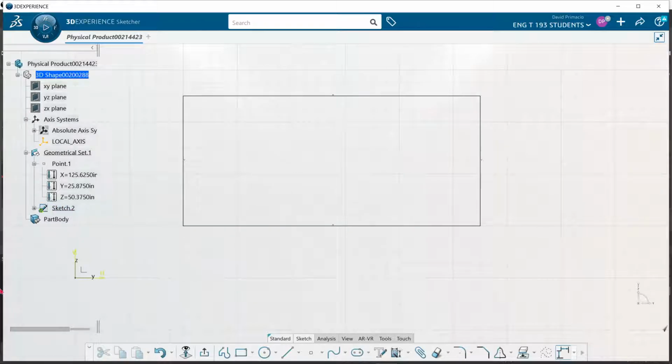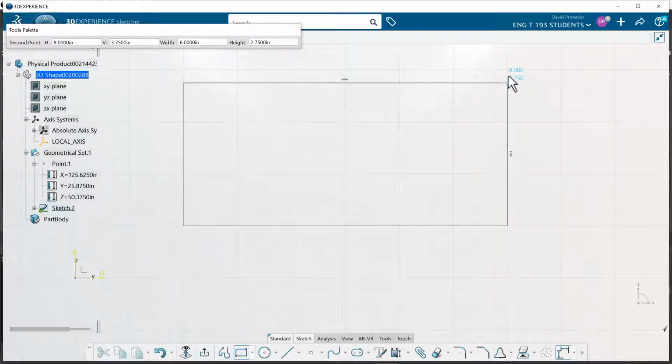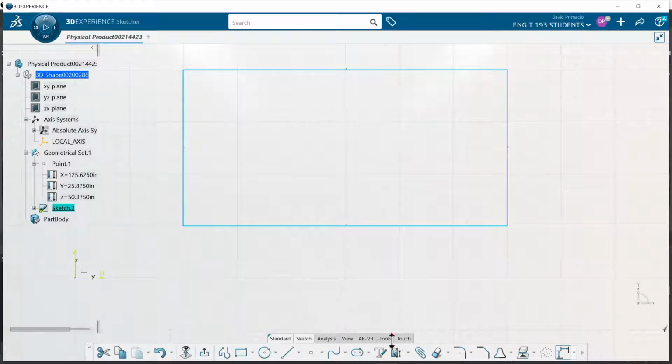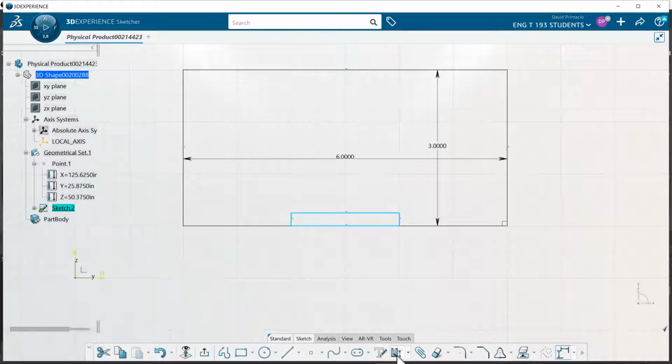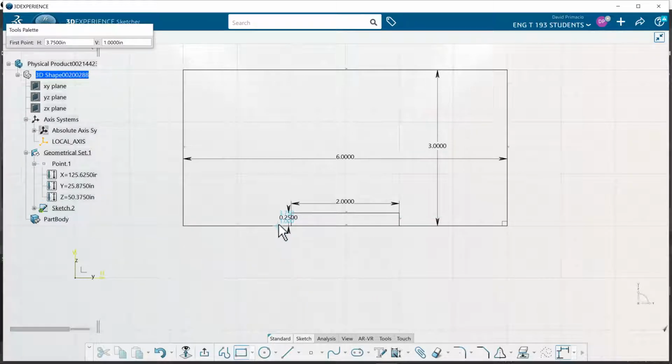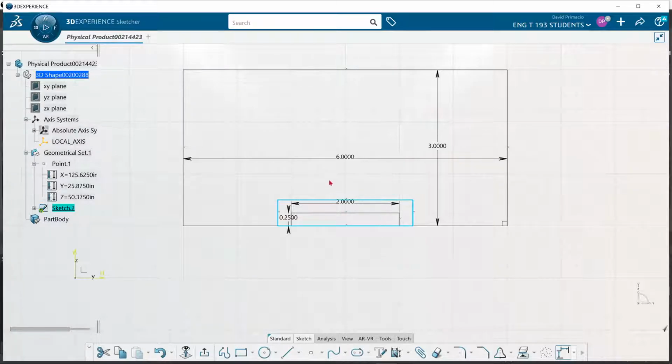So if I were going to do this, what I would do is when I create this first rectangle, CATIA does auto constraints really well on boxes. I just hit that and hit OK and just let it do its thing. I'll create another rectangle, and with it highlighted, hit auto constraints and just say OK. What I'm doing is I'm just controlling the size of the boxes that I'm putting in there. And with that one highlighted, I'm going to say OK under auto constraints. So now I've got my boxes highlighted here.